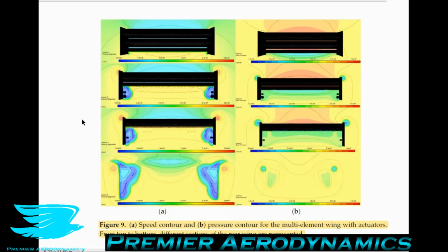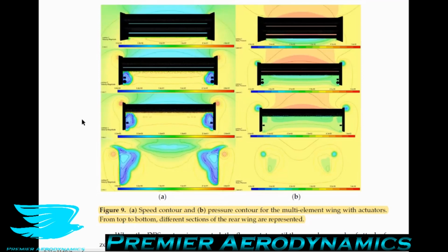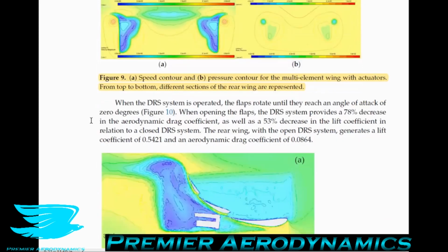I should mention that vorticity is not the be-all and end-all to a vortex. In fact, it may not even indicate that there is a vortex there. They could just get vorticity from the surface. But higher vorticity means that if there is a vortex there, it's more concentrated. If there isn't a vortex there, there's still a concentration of flow circulating around a little bit. And that means that there is often going to be flow around that being induced as well in this direction. The higher the vorticity, the more it's going to pull more flow from around it into it and make it circulate around as well.